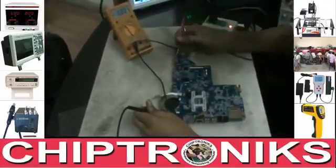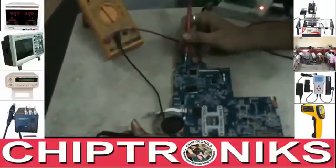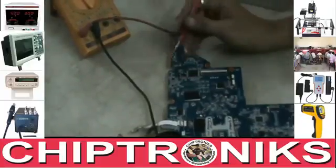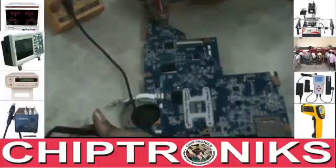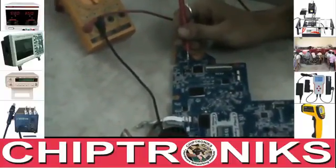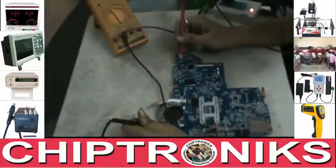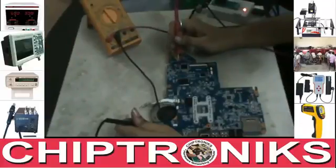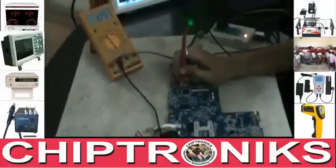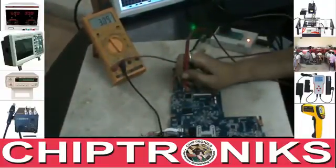Just look over here. I'll check pin number 8, the VCC pin. Here I need to check for 3.3 volts. 1, 2, 3, 4, 5, 6, 7, 8. You always count anti-clockwise. This is pin number 8. Here we get 3.3 volts on pin number 8, the VCC pin.